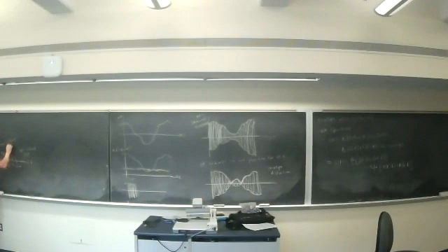Or LSB. Now, you can kind of see here, you might ask the question, well, those are awfully similar. If I have one, can't I generate the other? And the answer is yes. Okay. So do I need both to transmit both of these? And the answer is no. I only really need to transmit one, the upper sideband or the lower sideband. Those are called single sideband modulation methods, and we'll look at those. Those are more complicated. They require more complicated receivers. But standard AM radio is a double sideband method.